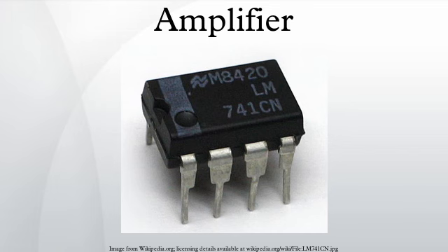An improvement is to bias the devices so they are not completely off when they're not in use. This approach is called Class AB operation. Class AB is widely considered a good compromise for amplifiers, since much of the time the music signal is quiet enough that the signal stays in the Class A region, where it is amplified with good fidelity, and by definition if passing out of this region, is large enough that the distortion products typical of Class B are relatively small. The crossover distortion can be reduced further by using negative feedback.